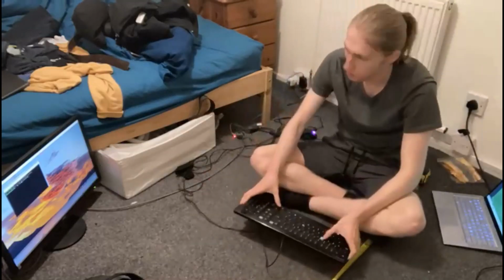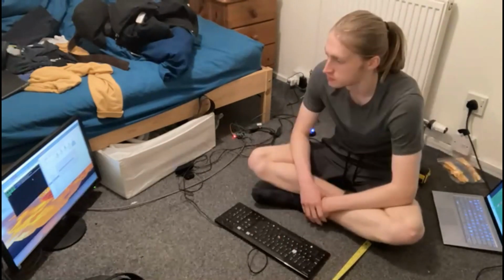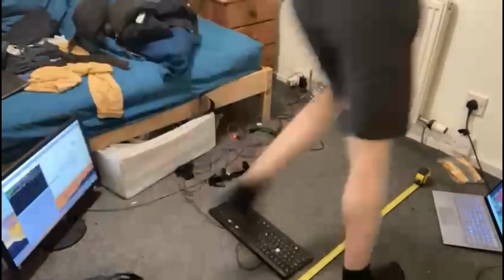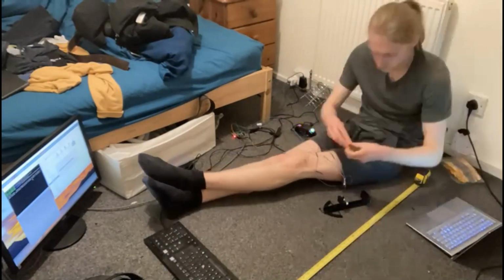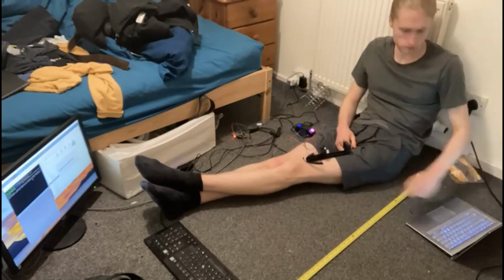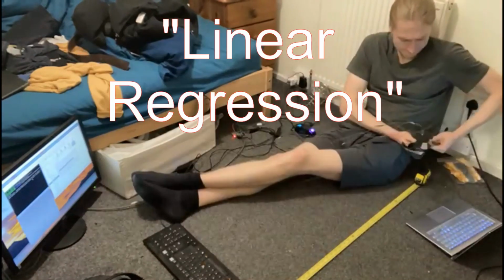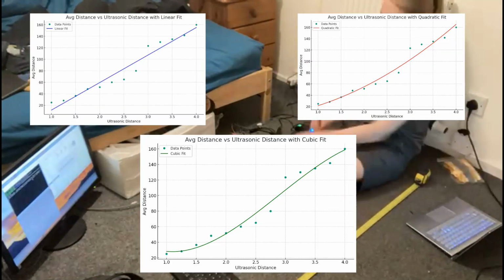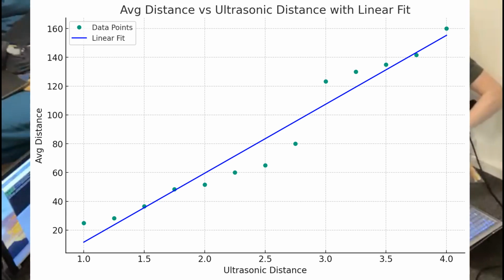Oh, nice. All that's left to do now is create a system that maps how far I pull the push shaft back in relation to how far a projectile actually travels. Now I could have used some sketchy equations for this, but they all relied on ignoring friction, which just was not realistic for the crossbow. So instead I did some testing and results plotting. I used a cheeky bit of linear regression to map some curves to my data, and I ultimately chose the straight line method because it gave me one value for pulling distance as opposed to 3.